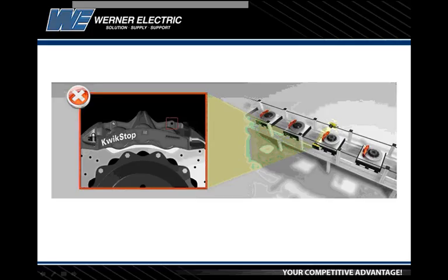But once you get into the territory of having 4 or 5 photo eyes mounted around a machine and having to individually fixture each one of those, that becomes very difficult to maintain. One of the advantages of machine vision is what different people call software fixturing or dynamic location, or there are many different names for it.